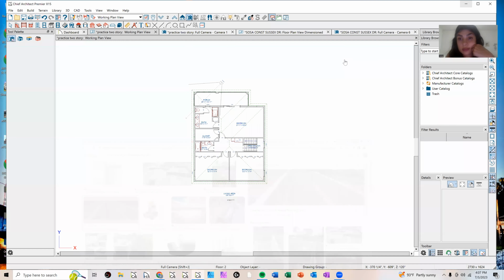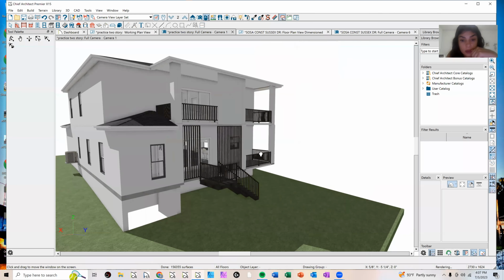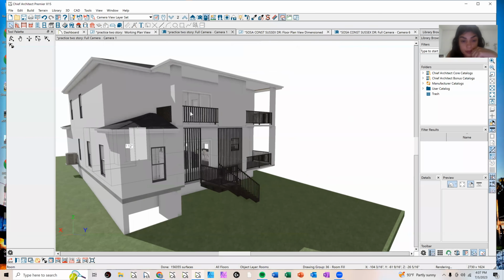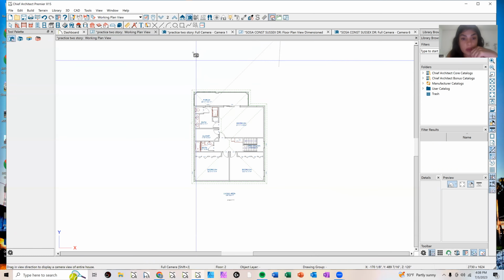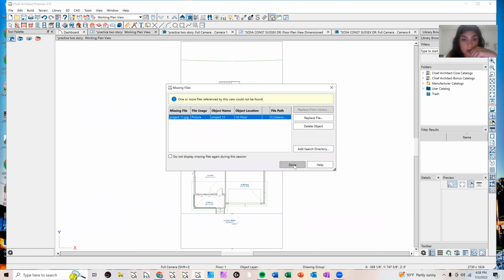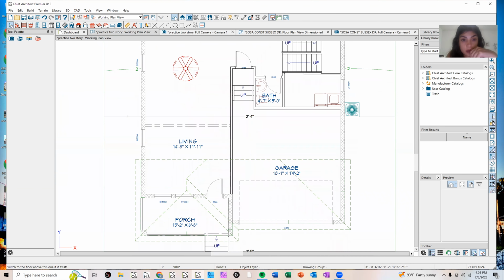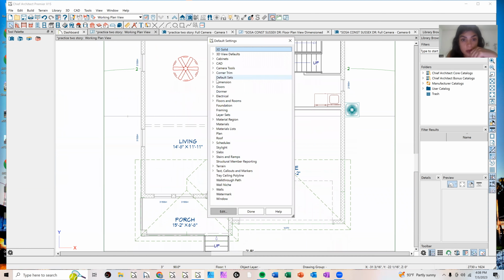So what we're doing on ours is basically the same thing. All this is just a stem wall foundation, and inside the house is all full of dirt. All this is filled with dirt. And then the slab here is poured over the top. But rather than drawing a whole foundation, the way I do it is I just make the floors. Let's do it in here. I just make the floors thicker.